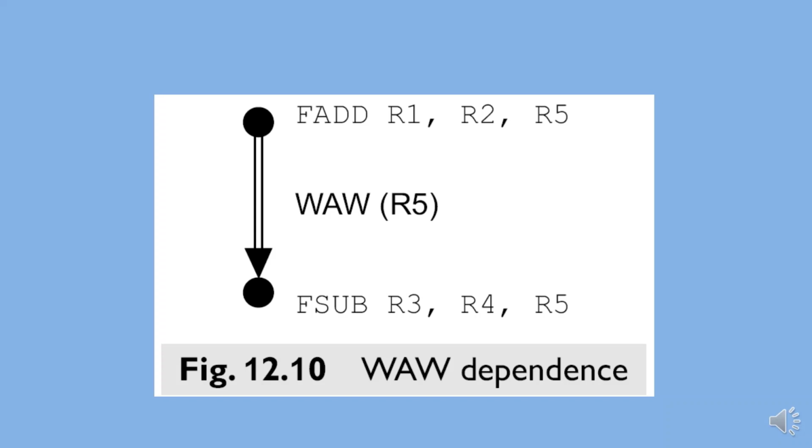If any instruction other than ij is also writing into rk, then that instance of rk will be mapped into some other program invisible register xn.